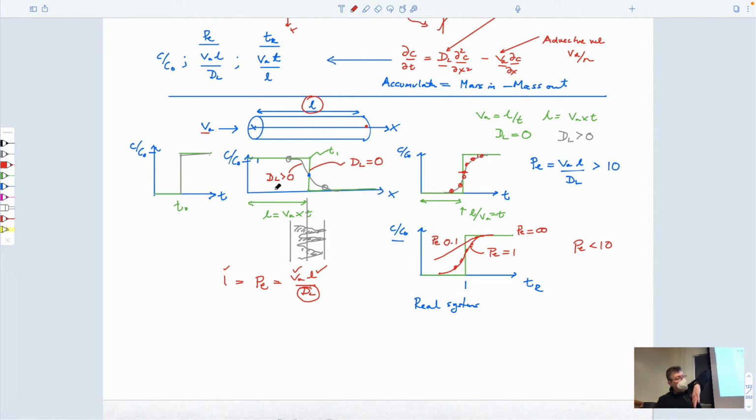And so as it becomes more dispersive, the inclination of this curve gets flatter and flatter, meaning that there's more mixing going on. The reality is that this mixing is due to the fact that in an aquifer you get lots of lenses of contrasting permeability, maybe by deposition. And so the solute will tend to go down the fast flow channels, and those will advance the tracer much faster than in the intervening low flow velocity layers.